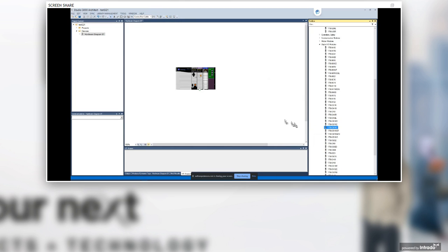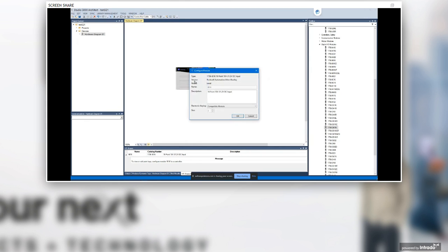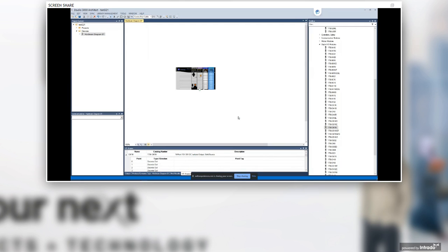And using the functionality of Architect, I'm just going to simply map these blocks to the controller. So now they know who they are controlled by. And I'll do the same thing for my output card. And once I've done that, so I'm using the Rockwell proprietary system, and Rockwell knows which controllers fit to which, so I would get error messages if I'm not using the right hardware, or it actually probably wouldn't allow me to put these systems together. So I'm using the Rockwell intelligence to create my configuration.